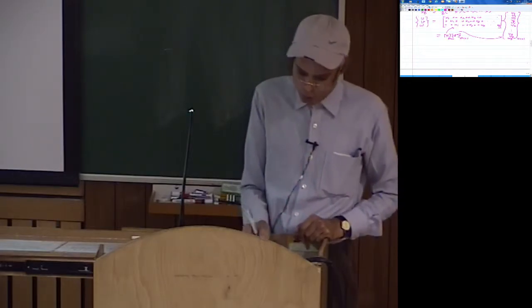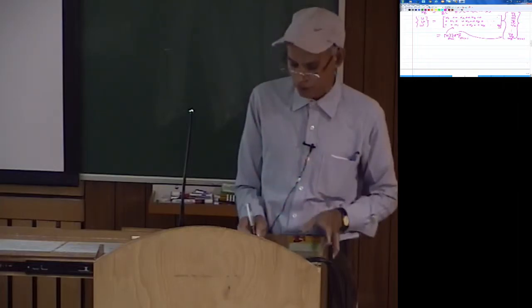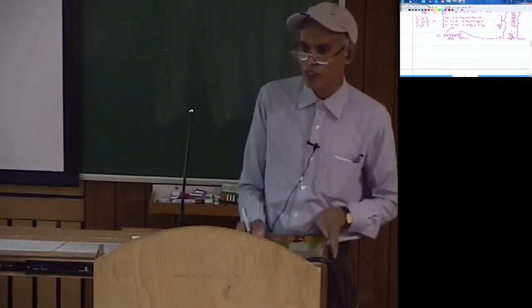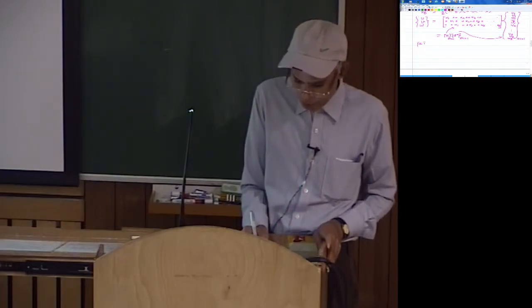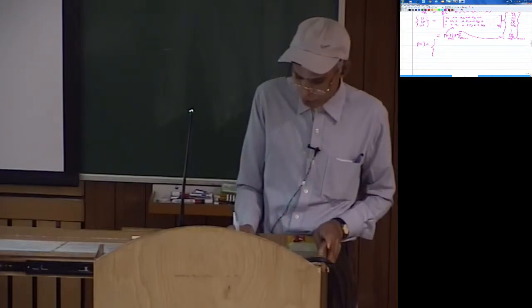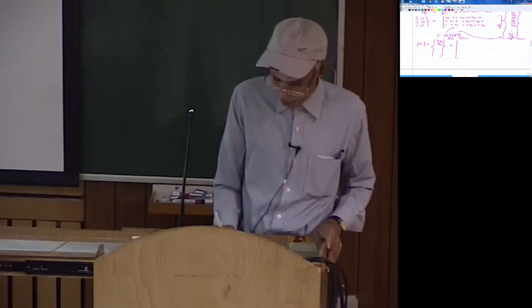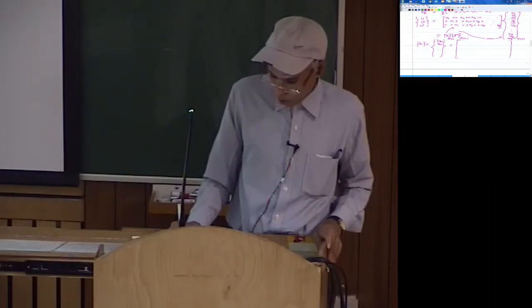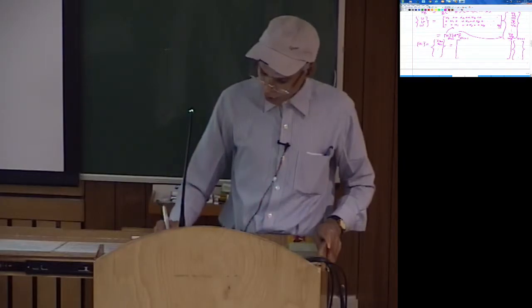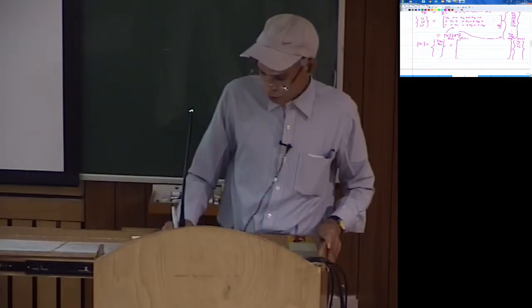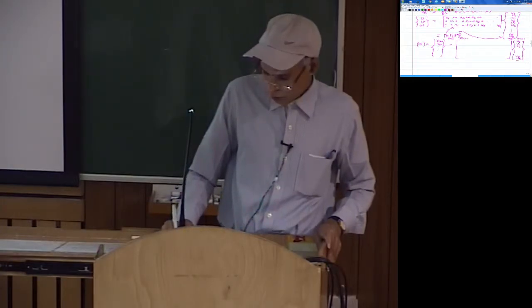Then what we need is, in the integral functional you have the strain vector. Now this strain is a tensor, but we have written it in a vector form using all the 6 components. So we are saying that the epsilon, which is all those 6 components, I am not going to repeat all of them again. So epsilon xx, epsilon yy and so on. So we want to again write this in terms of derivatives of the shape function and your vector of elemental degrees of freedom. So it's here u1, v1, w1 and so on, and finally you have u8, v8 and w8.